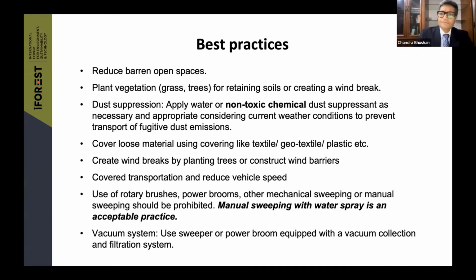And as I said, if you are going to use mechanical technology, then use a sweeper or power broom which is equipped with vacuum collection and filtration system. A lot of cities are now buying these automatic mechanical sweeping and dust collection systems. Please make sure to look at the quality of the filtration system and the collection system. Otherwise, it is of no use. So the specification of the filtration system becomes very, very important.